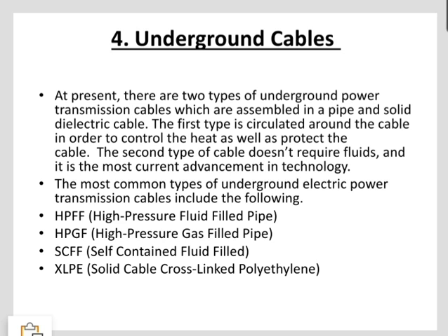Operations are more difficult since the high reactive power of underground cables produces large charging current and so makes the voltage control more difficult. Underground cables are more subject to damage by ground movement, and underground repair and checkup require street digging, and it creates patches and potholes. So these are the disadvantages.